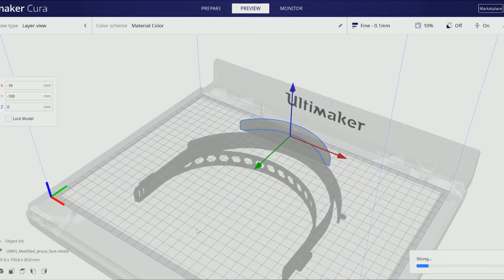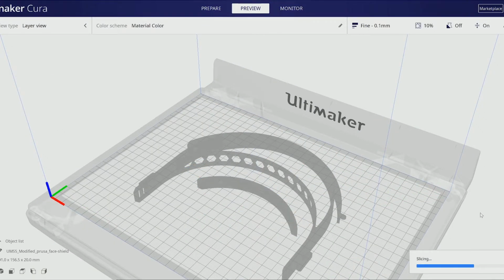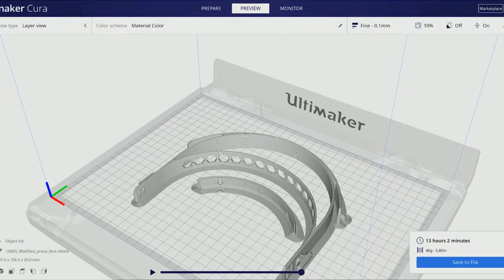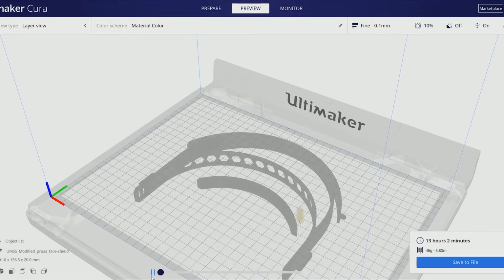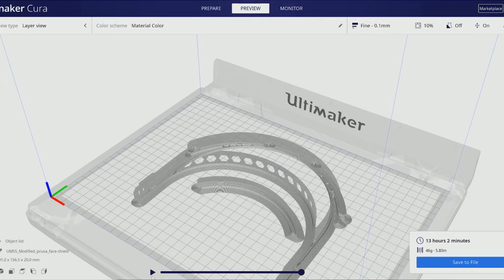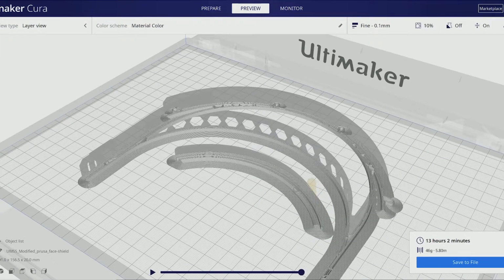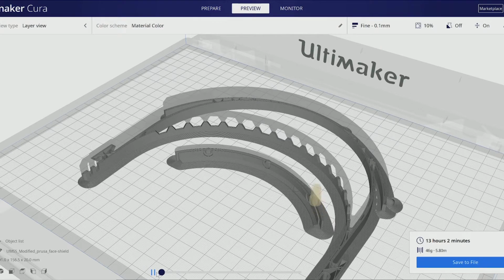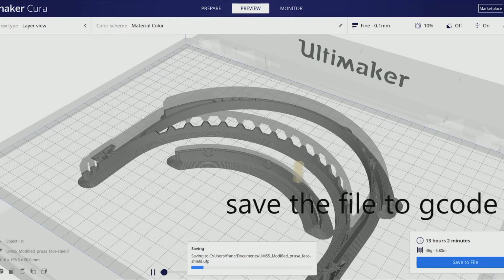One example that I'll be using is the Cura 4.5 slicer. As I'm going to demonstrate, this software will slice the object per layer, then map out the movement. The slicer will also be where you input all your preferred settings. I'd recommend sticking to what your slicer recommends before tweaking each and every single setting available for tinkering. But of course, as you progress, you would learn to tweak a bit of this and that. With this, the next thing to do is slice and export the G-code.